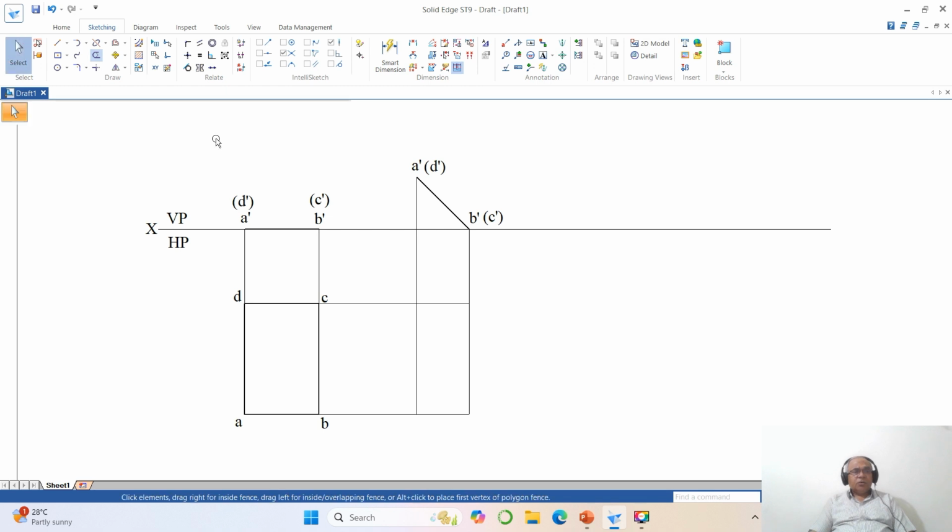Then what happens now, if I select this, all these things are entirely getting selected. So what I want is to make it dark only till here, and from here to here it is dark, from here to here. How to do that? First you go to split this line, till where? Till here, the intersection. Similarly you split this line till here.